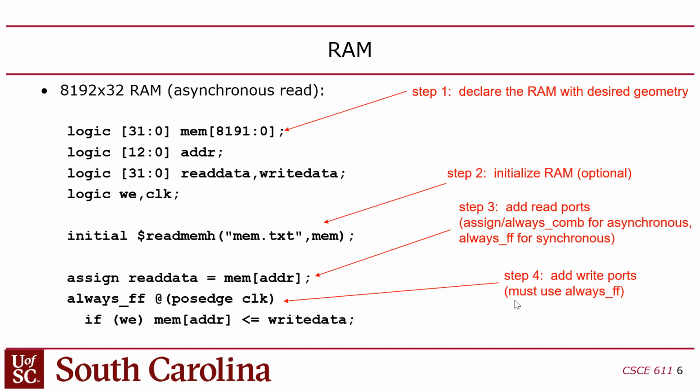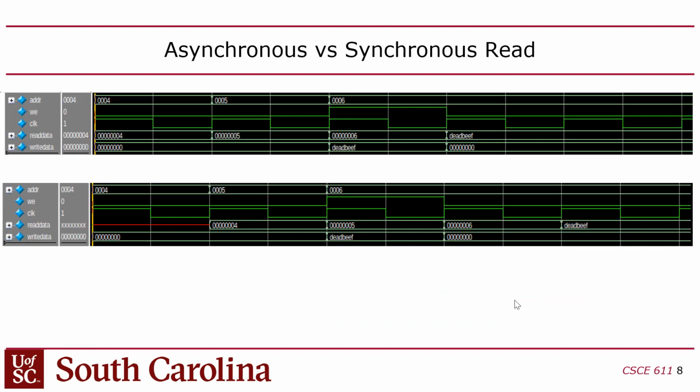You guys with me? So in other words, what I'm trying to say is that you can implement a RAM behavior in Verilog, right? But that doesn't necessarily mean it's going to target a specific RAM on the FPGA. Sometimes you have to restrict yourself in the behavior of the RAM, right? Okay, so if that's confusing, hopefully I can clear that up a little bit.